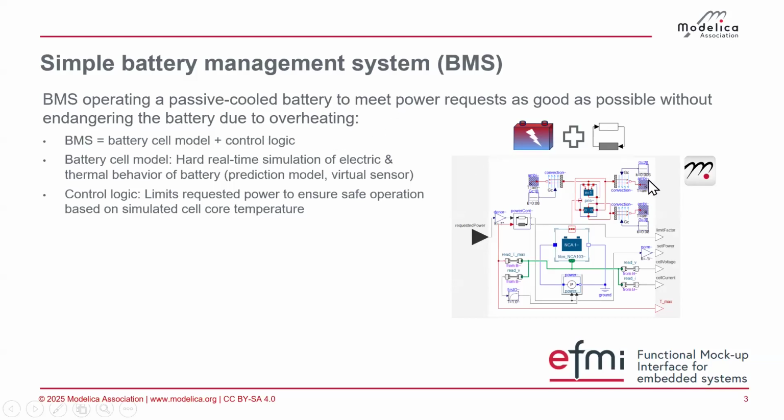This is all done in Modelica. So we have the battery cell model, which is a hard real-time simulation of the electric and thermal behavior of the battery. It's a prediction model, a virtual sensor, a virtual twin. These are the terms people use. And then in this model, we have the control logic. There's a controller, but that is very, very simple, because essentially you get a power request, and this controller will limit the power request to ensure the safe operation. It's nothing more. So the power controller is simple.